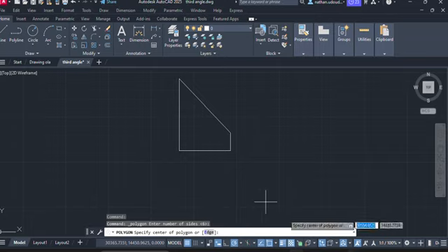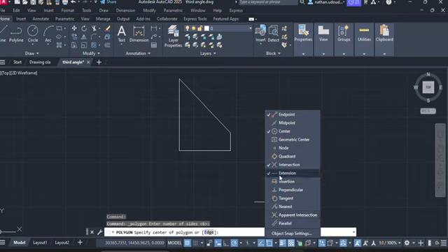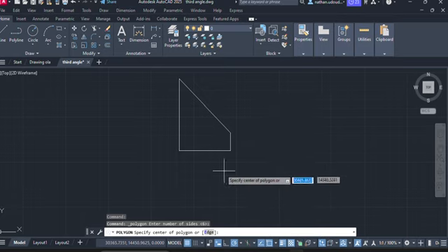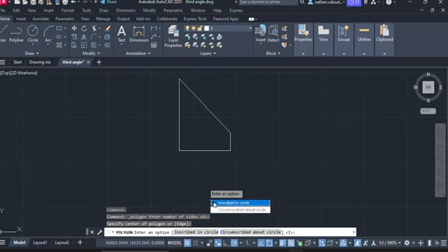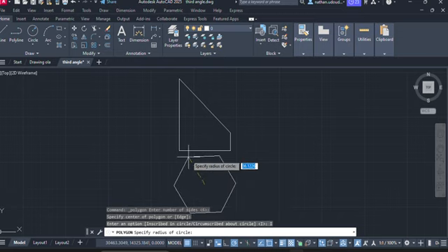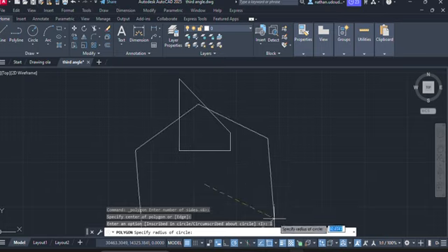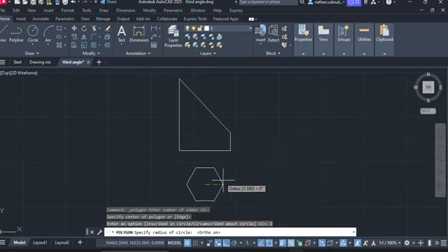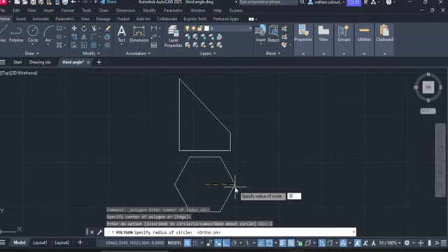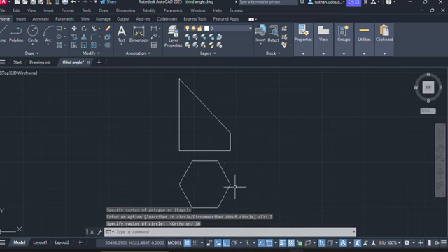So let's come to our object snap and then put in the midpoint. Okay, so midpoint is not there. So that's our midpoint. So now we trace it down. We left click somewhere here. So inscribe in the circle. Let's turn on our auto mode as well. So now we are choosing a radius of 30 mm, 30, enter. So now that automatically gives us the plan.